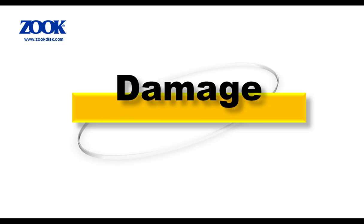Disk damage in the field is the single largest cause of nuisance bursts. I use the term nuisance burst loosely, and what I mean is a burst at a level lower than marked or expected. These nuisance bursts can still be expensive or result in significant loss of product or time or both, and they need to be avoided.